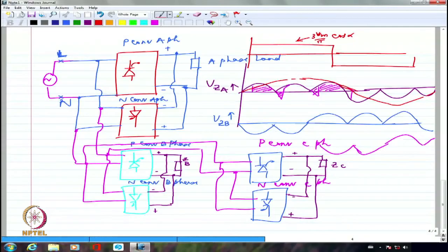So you are going to see that it takes a while before the speed changes even a little bit. So the response time is really, really large for a synchronous motor drive, which corresponds to megawatt level rating. SCR is also slow, and they can handle very large power. So they all match very nicely.